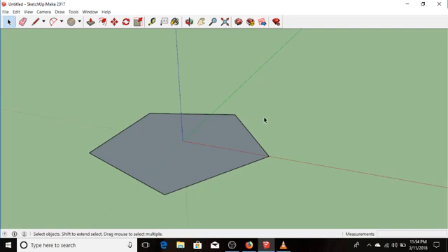This thing's going to have 12 identical sides. So rather than make it and then edit each of the 12 sides individually, I'm going to turn this into a component. When an object is a component, you can make multiple copies in your build, and when you edit one, all the other copies of that thing are simultaneously edited.